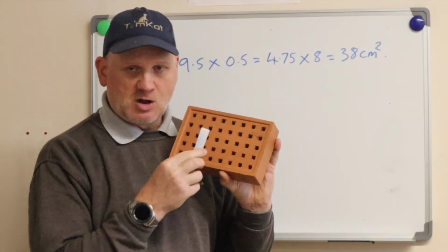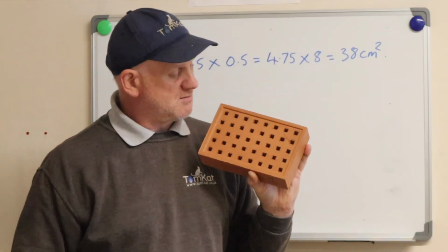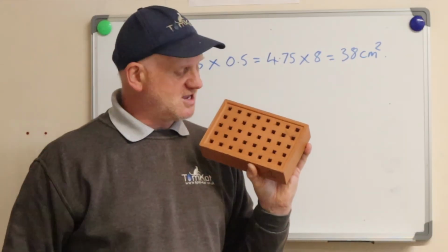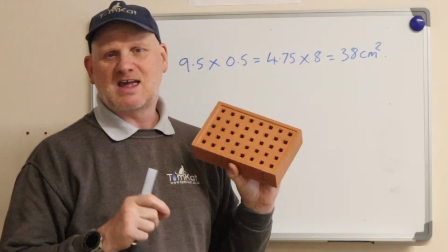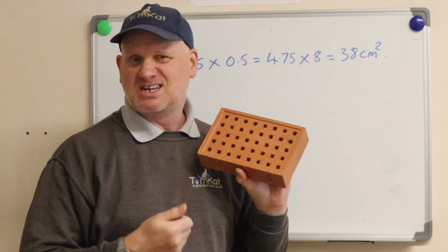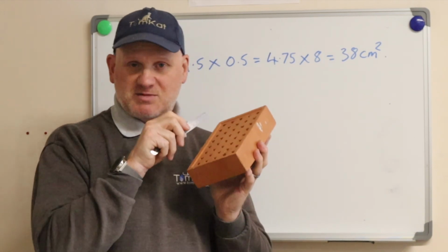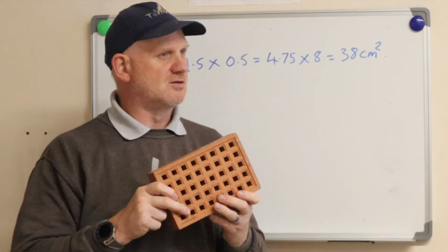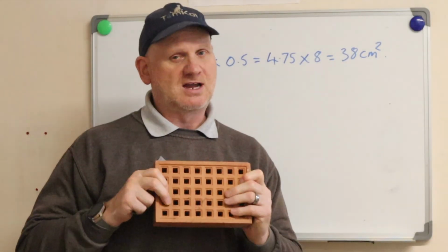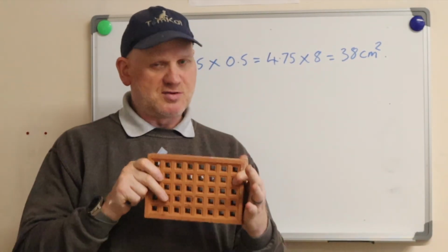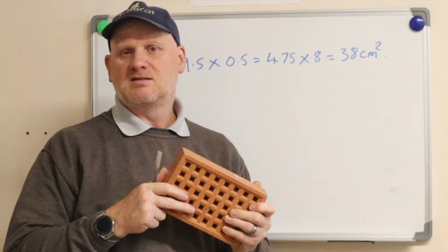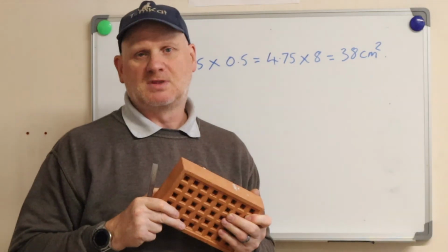Now the size of these holes obviously can't be more than 10mm. So a bit of a cheat you could do nowadays if you didn't have one of the gauges is you could get yourself a 10mm drill, and if it doesn't go through the hole then you know it's 9mm like it should be. But you have to measure the back of these, not the front. So these are now also classed as not good enough for gas vents. But like I say, if they are in and they're bridged, and you can check that they're less than 10mm, then they can be deemed okay.